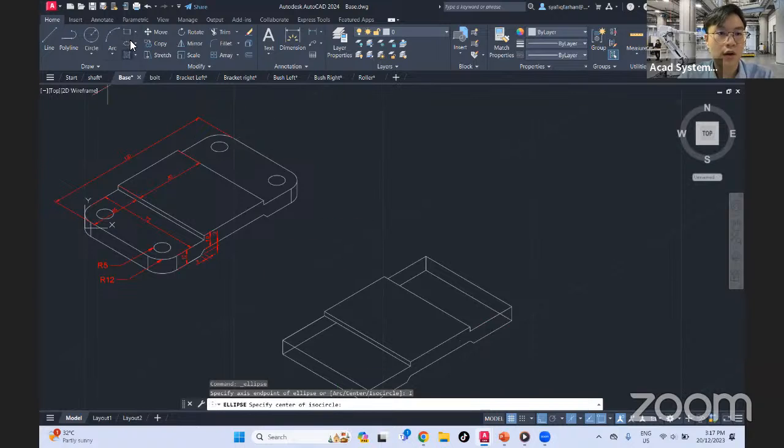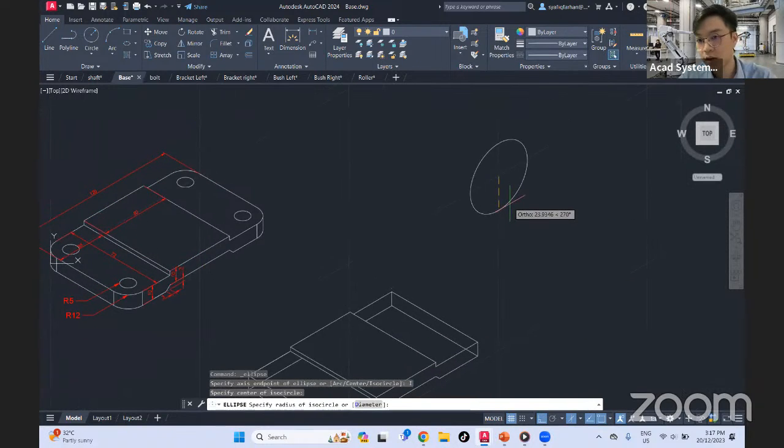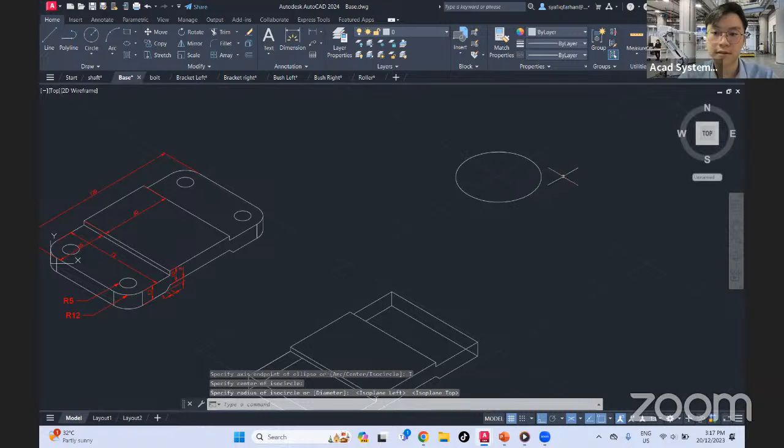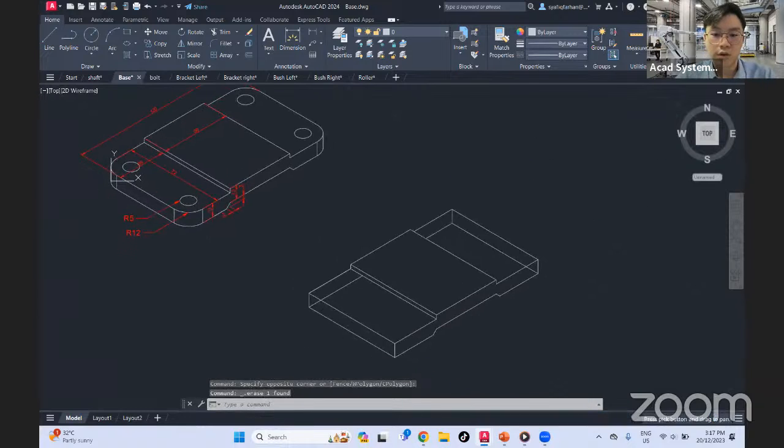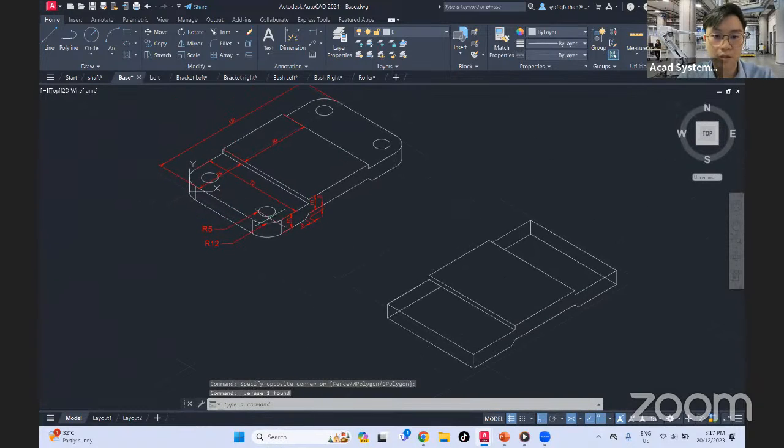So once you have entered these settings, it's basically the same as how you normally would draw a circle. Specify the center of the circle and draw. So right now you notice my circle is actually snapped onto the plane correctly. If I were to change my plane, you notice right now it's snapped onto the left plane. And if I click on F5 again, it will snap onto the top plane. It's just that. So right now, my circle has a radius of 5.